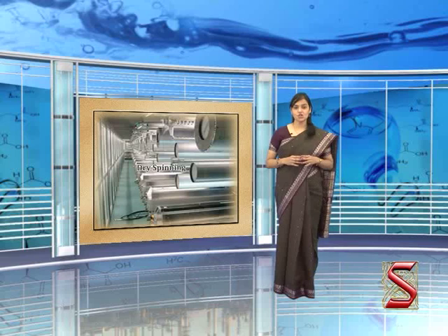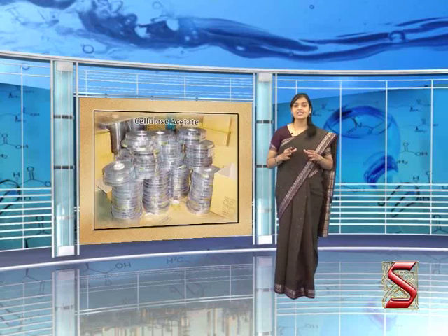Mostly, nylon and rayon fibers are examples of this process. Unlike this method, in dry spinning, the polymer solution in a low boiling solvent is pumped through a spinneret. Then the solvent is evaporated by hot air outside the spinneret, leaving the polymer fiber. This method is mostly used for cellulose acetate and Orlon.